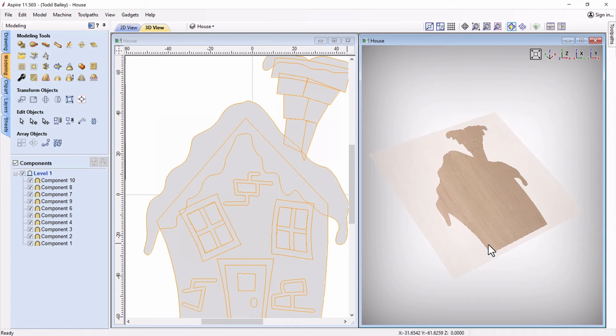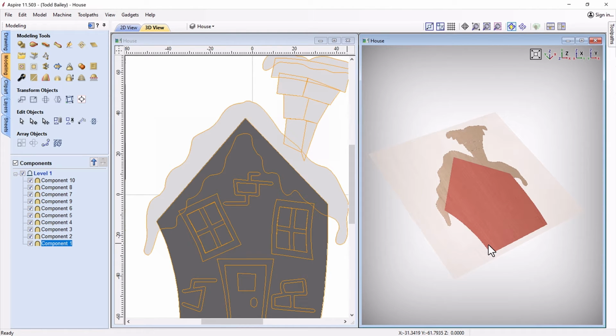First thing we're going to do is double click on our 3D view, select the house here, and click it again. That way we'll reveal our control handles, along with this new little gadget in the corner that arrived in 11.5. Normally there would be this box and then a little arrow on top of it. If you pull the arrow up and down, it would change the shape height. And if you move the box, it adds base height.